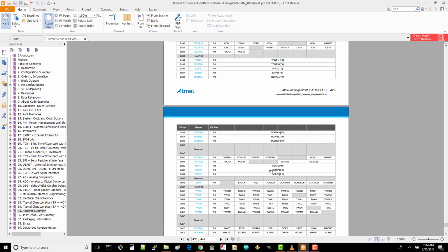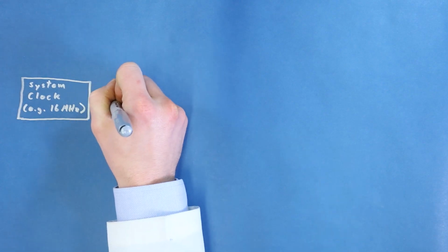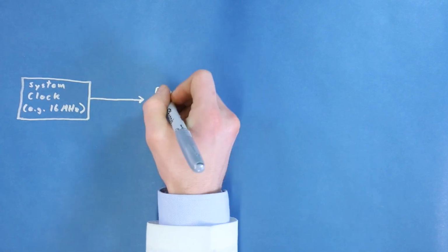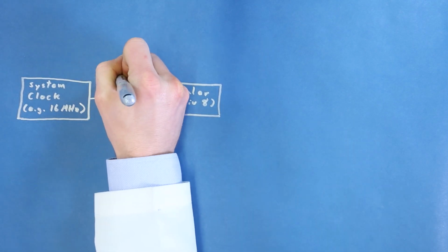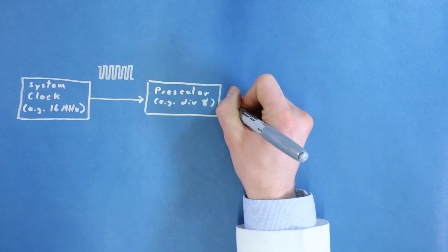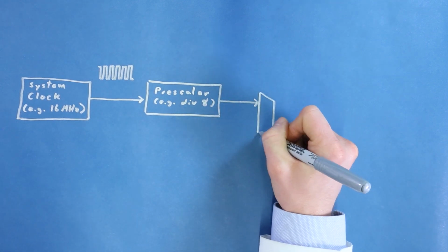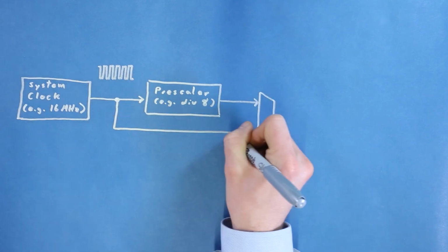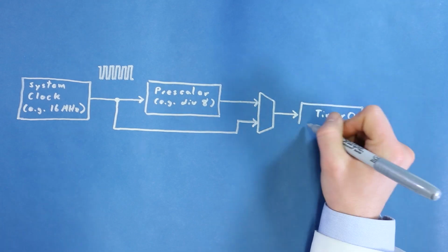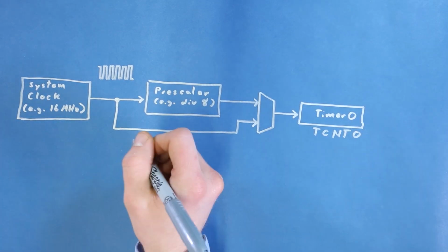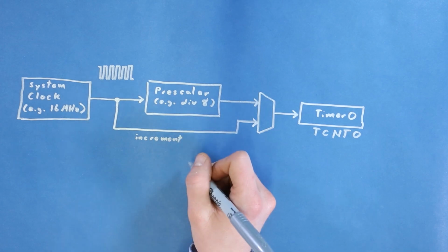Let's see how these timers get automatically incremented without any code. Each of these 3 timers can be directly or indirectly connected to the system clock. The system clock is a square wave that is produced internally in the microcontroller based on your settings. It could be generated inside the microcontroller itself or from a connected oscillator or crystal. The system clock is vital to the operation of almost everything in the microcontroller. The Arduino Uno, for example, has a 16 MHz crystal connected to the microcontroller. The 328P generates a 16 MHz square wave from this, which is used to feed many functions, including our timers.